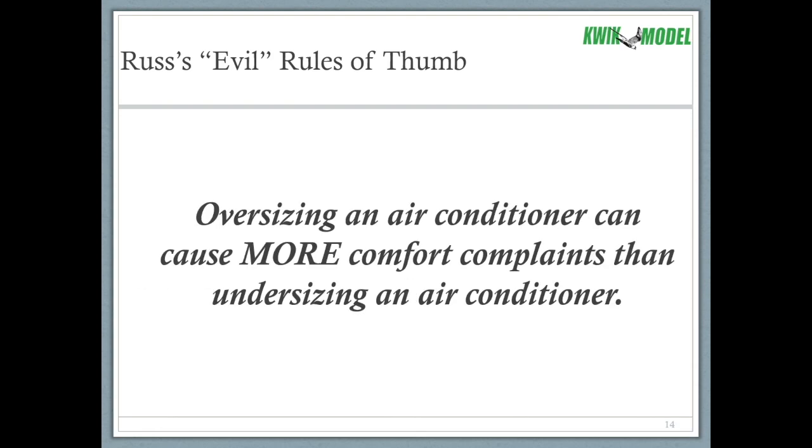The first one: oversizing an air conditioner can cause more comfort complaints than undersizing an air conditioner. A lot of people think that bigger is better. I'm not sure how this homeowner is going to occupy this house, how they're going to use this system, so I'll put in a little bit of extra capacity. But what that ends up doing is actually causing more comfort complaints.